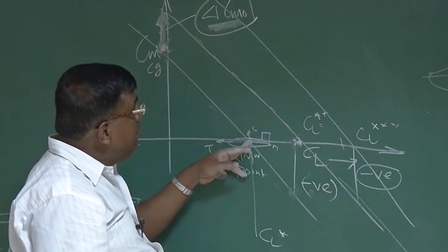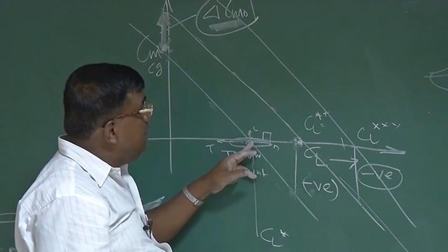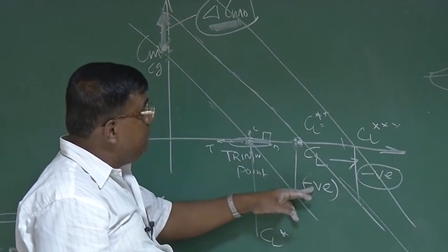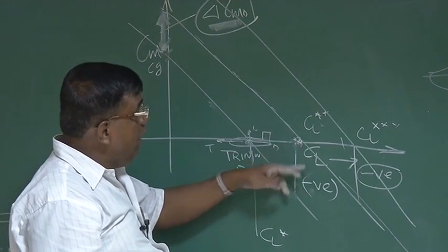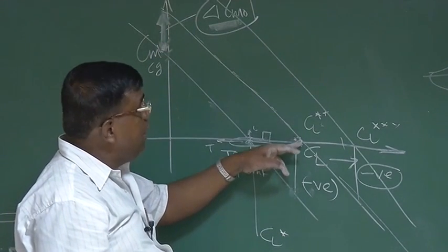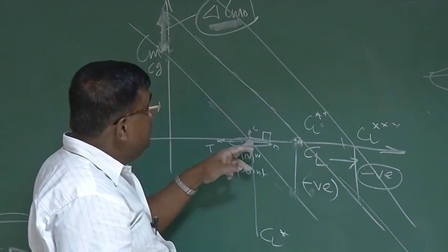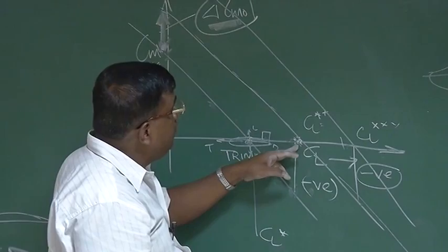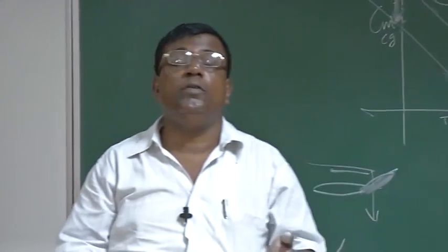So when I want to go from this CL to this CL, because this is statically stable at this equilibrium, it will generate opposing moment. To fly here, with Cm0 I have to generate positive moment. So I give elevator up. Same thing here. So from one equilibrium to another equilibrium to another equilibrium, this process is called control of airplane.